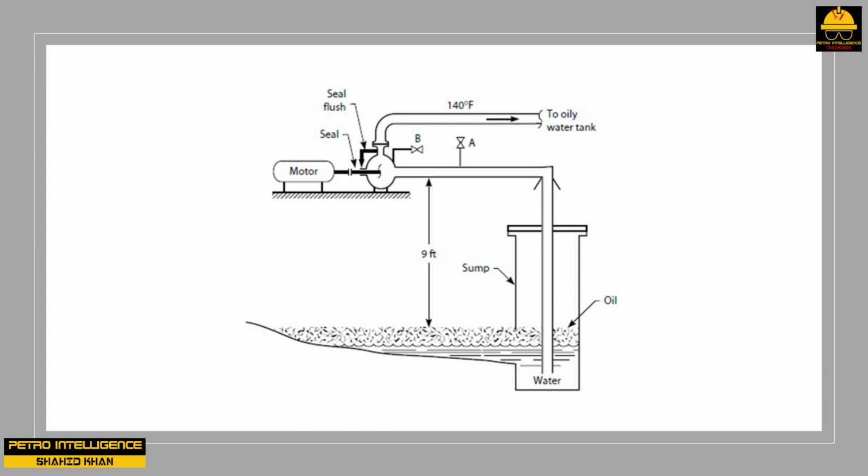The mechanical seals on centrifugal pumps require a lubricant or seal flush material to keep the seal faces from touching and rubbing. In most pumps, this seal flush fluid comes from the discharge of the pump itself. Such pumps are called self-flushed pumps. When a self-flushed pump is running, the space between the seal faces is filled with the seal flush fluid.